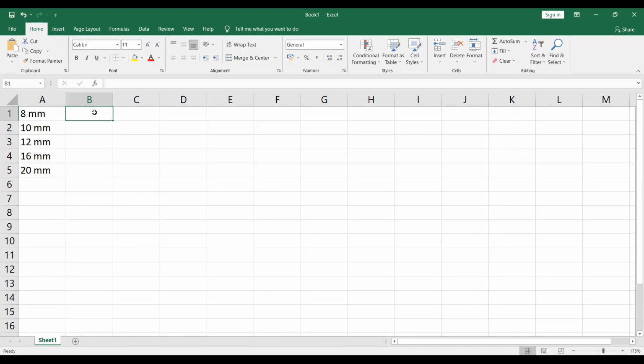π/4 into 8 squared. Okay, fine. π/4 into 8 squared. Do you agree with this? Yes. Okay, what is π/4? Sir? What is the value of π/4? 0.785, sir. Yeah. So see over here in the Excel sheet how we will calculate that 8 mm dia bar reinforcement area.